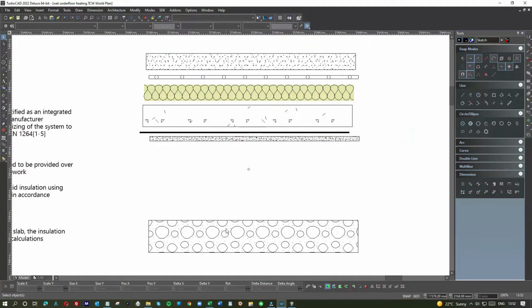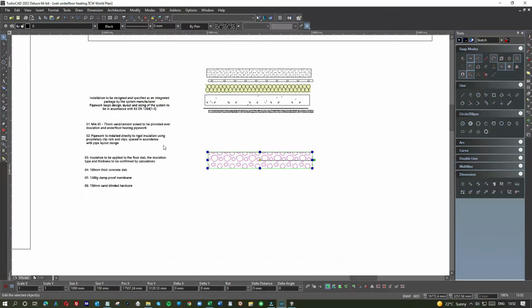What I was saying was that I actually created these little units this morning, these little bits and pieces. So what this is here is, it's on scale, by the way. It's 1000 mil wide, 150 mil high, and it's rubble. It's general rubble. This can be anything from brick to stones or broken up patios, anything that you've got that makes it up. But generally it's about 150 mil. You can see the sizes down here, and in any case the notes here will say hardcore.